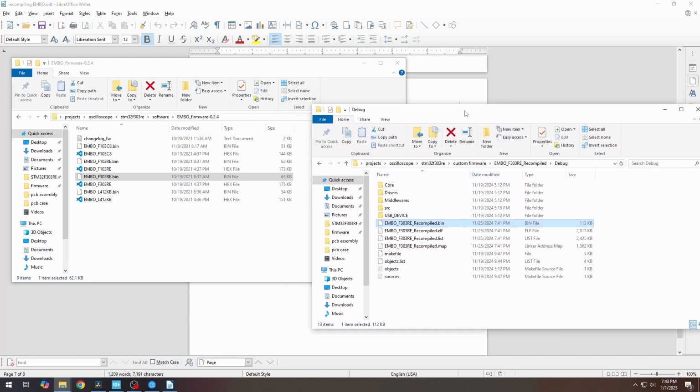If anyone has any idea why that happens, I know that I could have used a different firmware package for the STM32 in CubeMX, as well as a different CubeMX version and maybe different optimization flags, but I know the lower optimization flags are ones the code in the comments said not to use because it could break the RTOS. So I have no idea why these are different sizes, and looking at the disassembly, they're completely different.